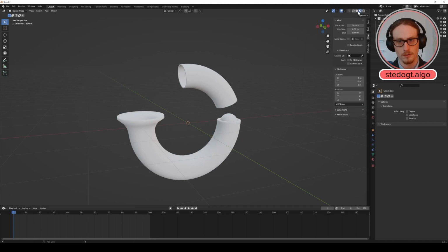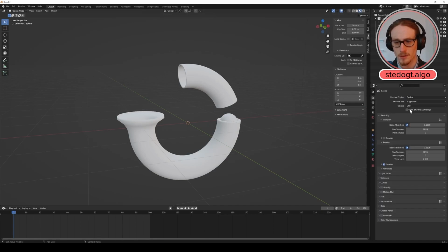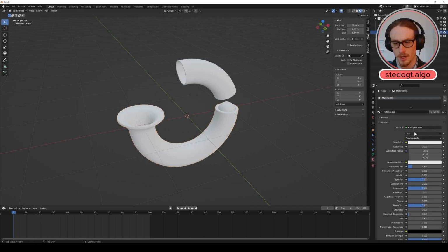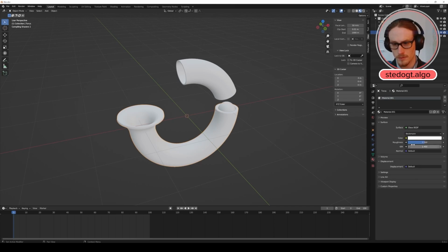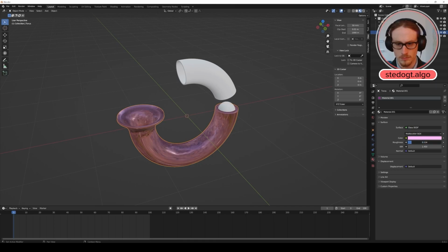First, before we start to visualize our materials, we're going to change our render over to Cycles. This render engine I'll be able to use with my GPU. And now I want to start applying, first I'll select my torus and apply a glass material. The default glass, I'm going to change it to multi-scatter. Give it maybe a pink color. And decrease the roughness.